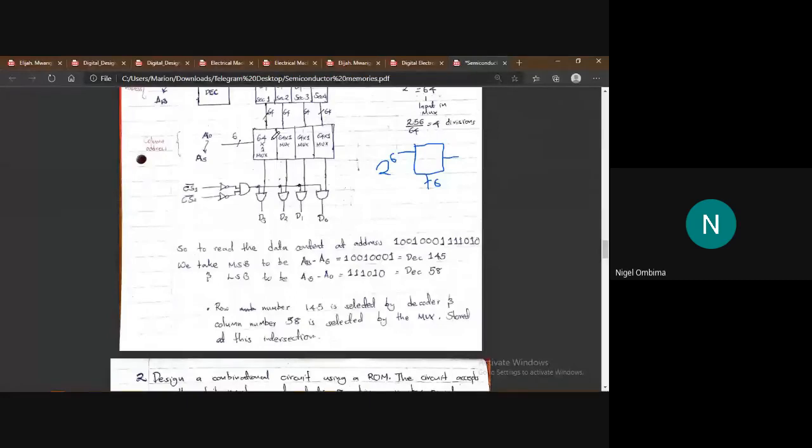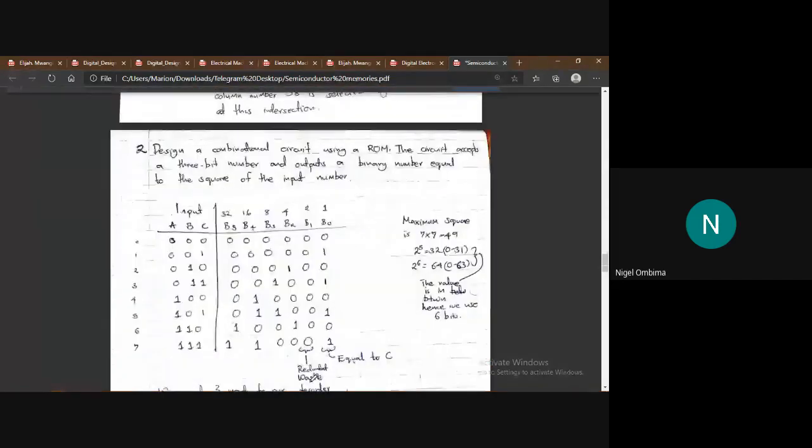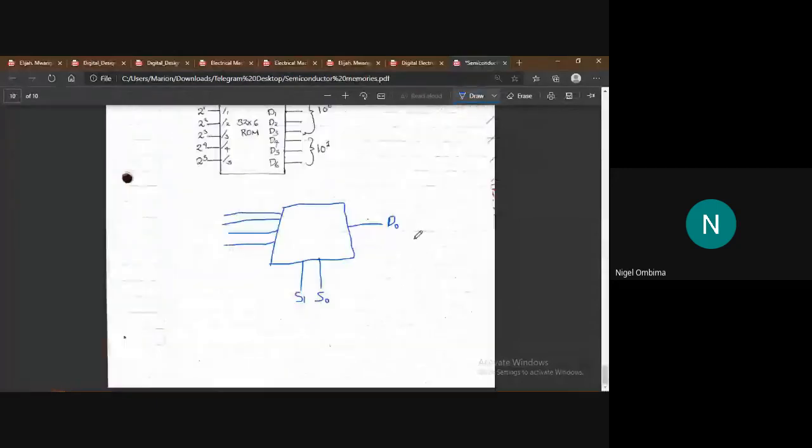The number of inputs is usually a power of 2, like here 2 power 6 is equal to 64. So 2 power the number of select lines gives us the input lines. Like here, we have only 2 select lines, so 2 power 2 gives us the number of input lines of our mux.